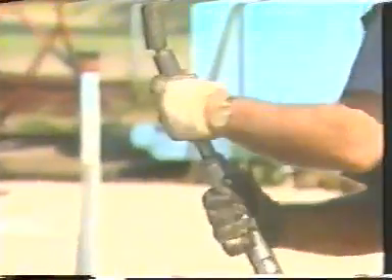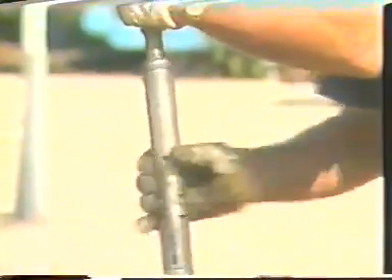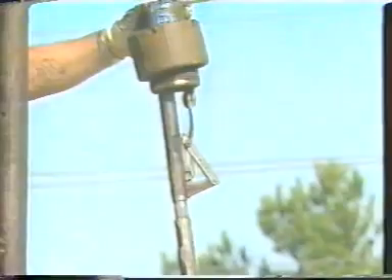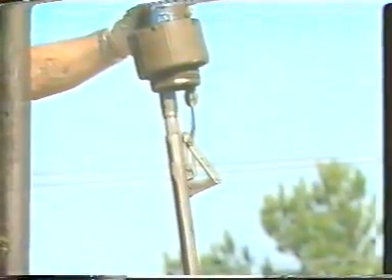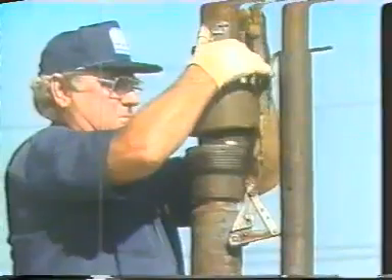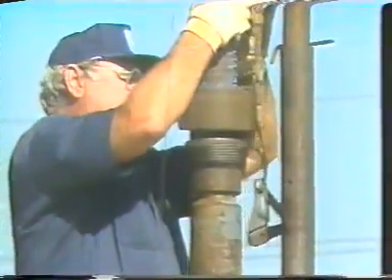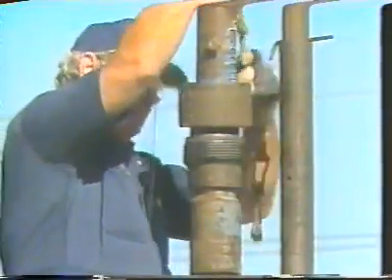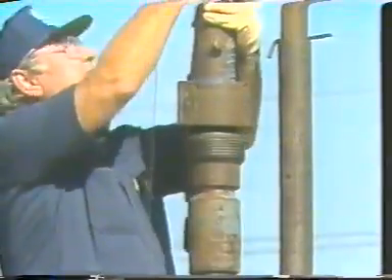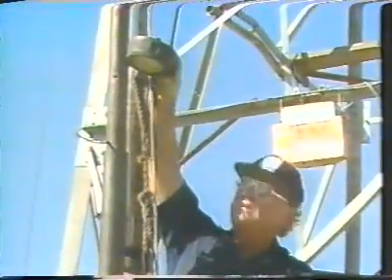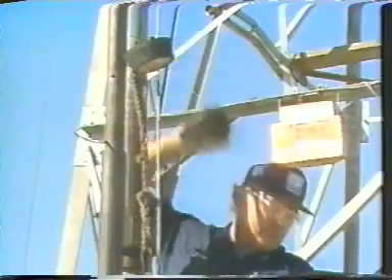The tool string may now be lowered out of the open lower end of the lubricator and the proper tool attached to the bottom of the tool string. After attaching the proper tool, the tool string is pulled up into the lubricator and the lubricator attached to the wireline valve. Before opening the valve on the tree to begin wireline operations, the entire lubricator stack should be tested. If any leak is detected during the test procedure, wireline operation should not be begun until the source of the leak is identified and corrected.